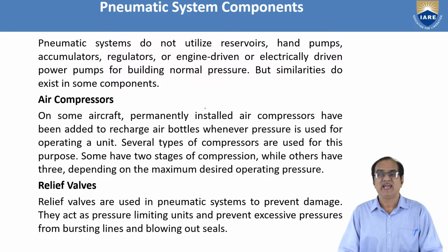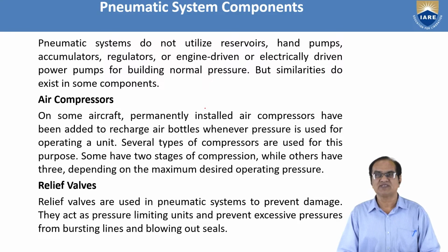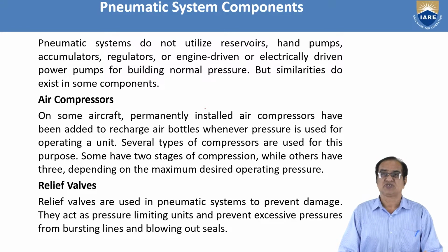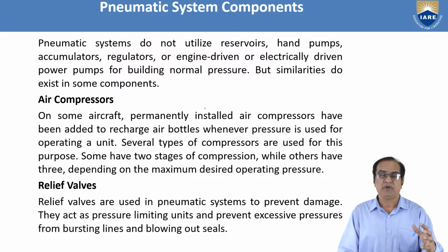So that is acting as a fuse. In electricity, we are using circuit breakers or fuses. So relief valves are acting as a fuse to prevent the system from high pressure in the pneumatic system.